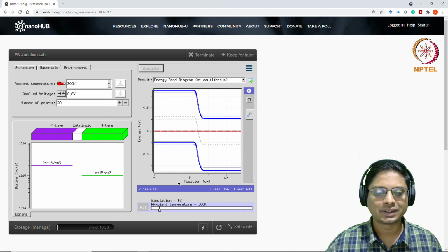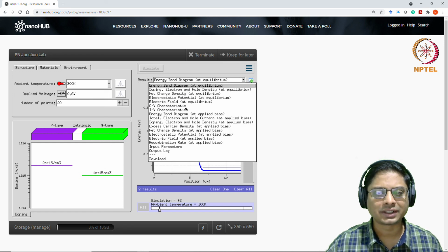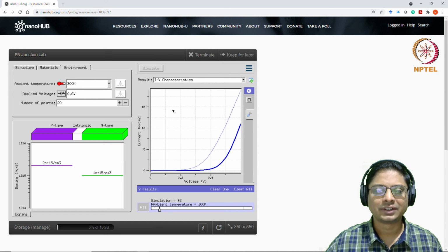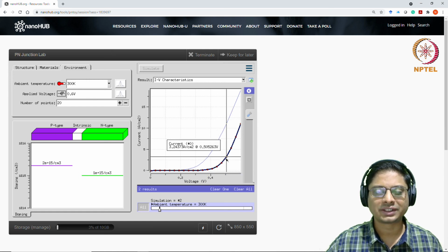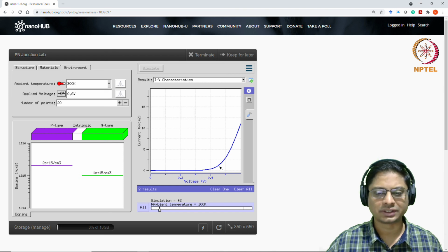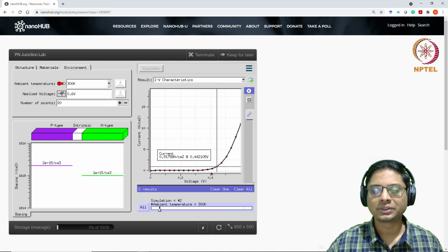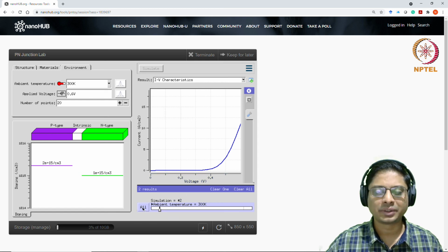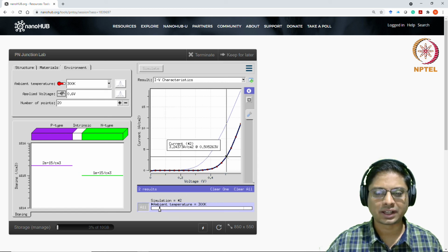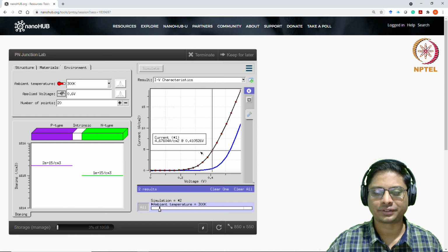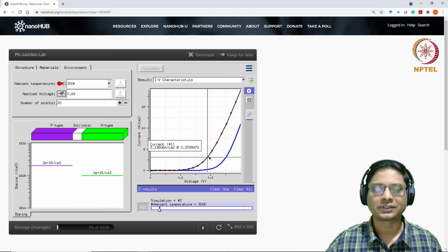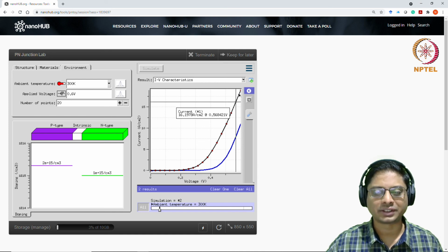Okay. And let's look at the current IV characteristics. So you see here, this was at 350. Sorry, yeah, this is at 300 degrees. You have threshold voltage close to 4.42 or something like that. And then the moment you included the higher temperature, the threshold has shifted to the left, as we have discussed in the last video, right? So the threshold voltage changes, and that's why you get a larger amount of current.